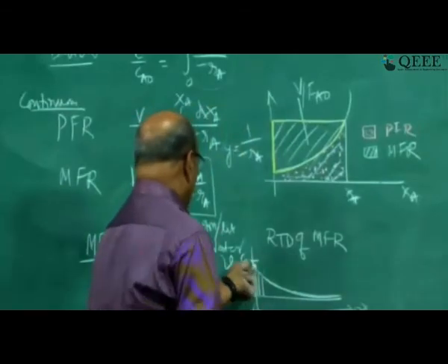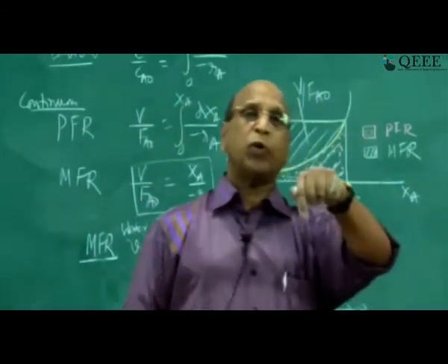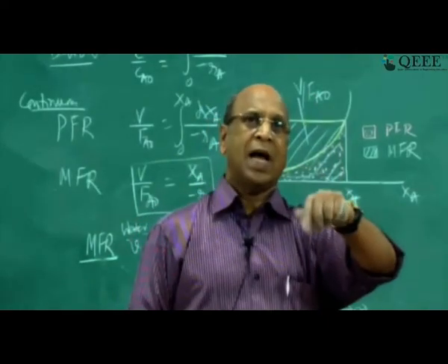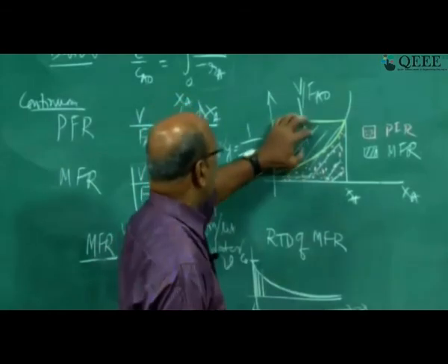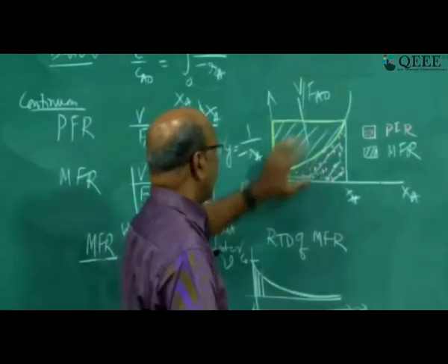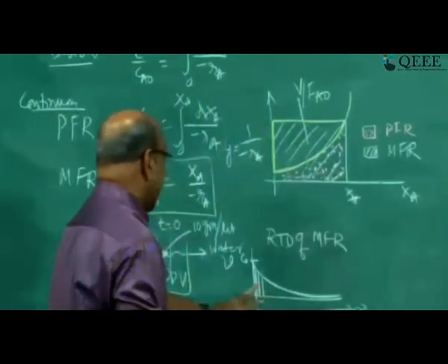Immediately a packet of molecules entered, came out. Where is the reaction? There is no reaction. That is why we are losing a lot of concentration, and to compensate that, you have to use a large volume when compared to your plug flow reactor. Now let us do the same experiment for PFR.